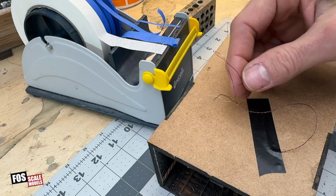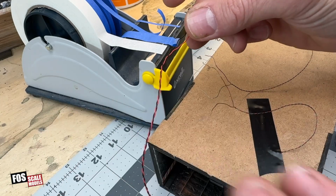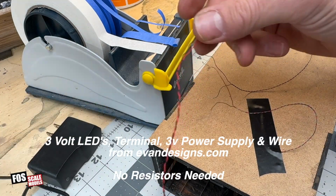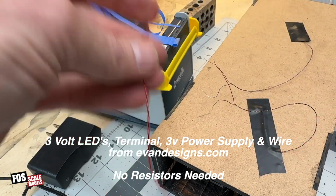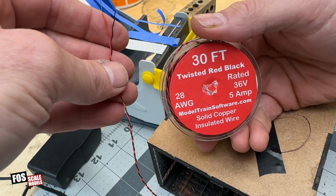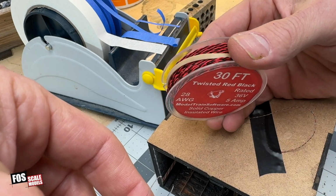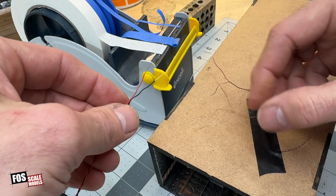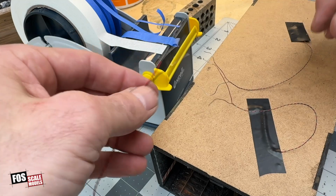So I need to wire this so they go to a larger wire, this one, and this is what will go to the terminal that'll be mounted under the layout somewhere. So both of these have to get wrapped around here and soldered to this, and this wire is 28 AWG. It's exactly what it says there, rated for 36 volts, 5 amp, and that's what you use to feed the rest of these LEDs. You could use these, but this is so thin. This is a lot more easy to handle when you're fishing it around the layout and wiring it up.